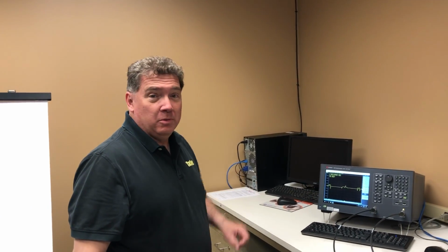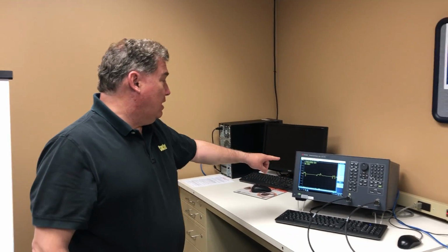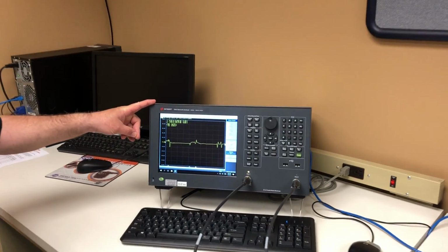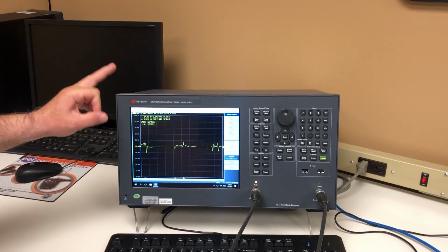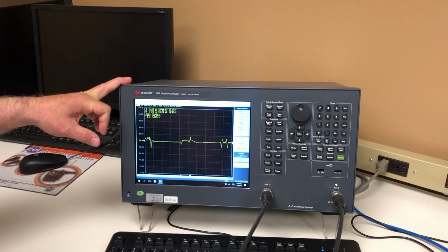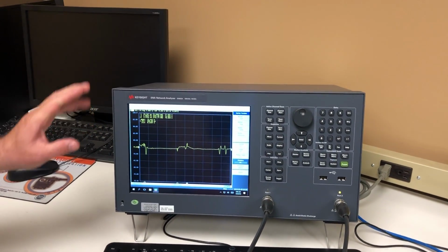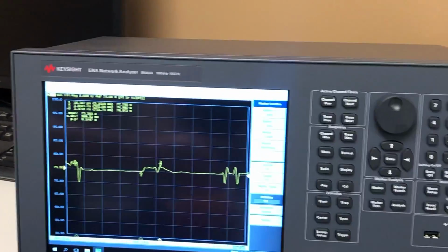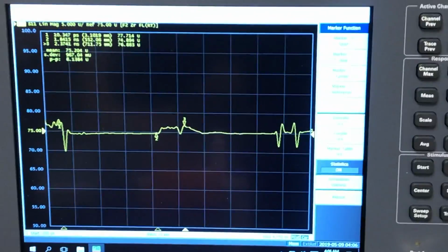I wanted to show you the rotary coupling for the CXP-12 cables that we have. This is our Keysight VNA. It has TDR function enabled, and we generally check the cables for impedance, and this is an impedance graph right now of this particular cable assembly.